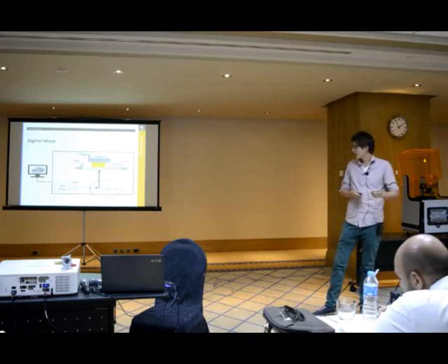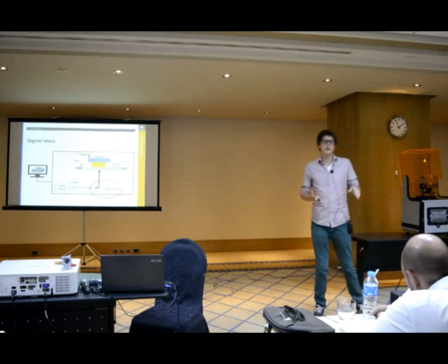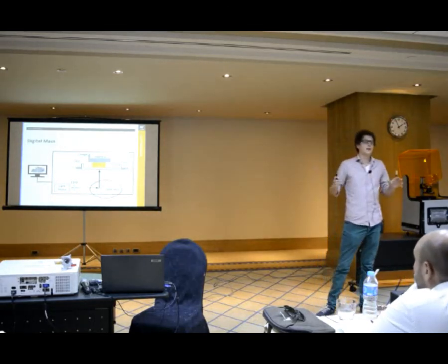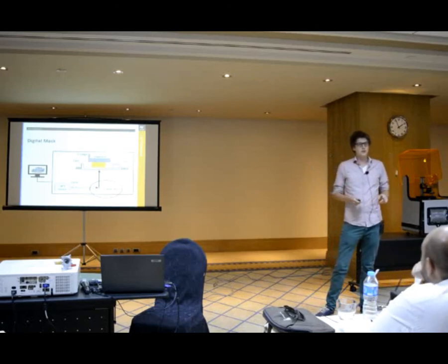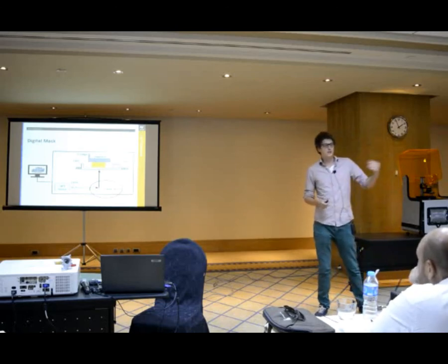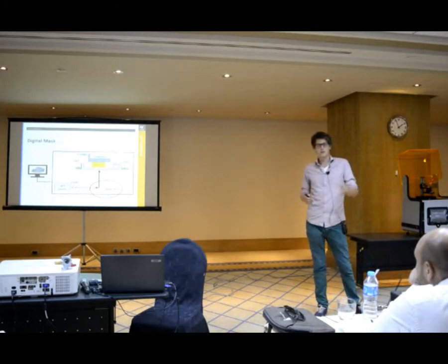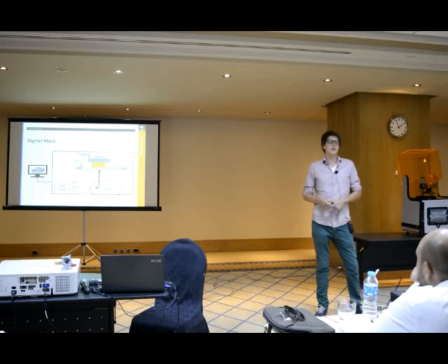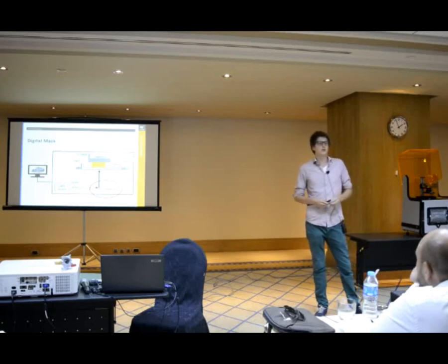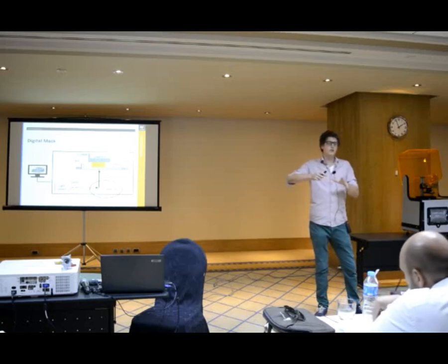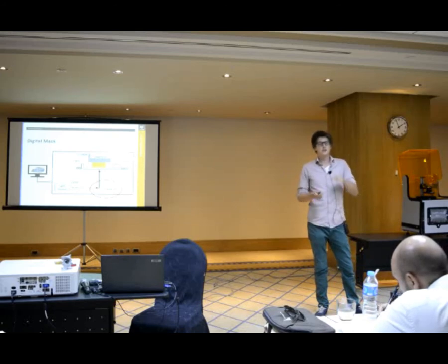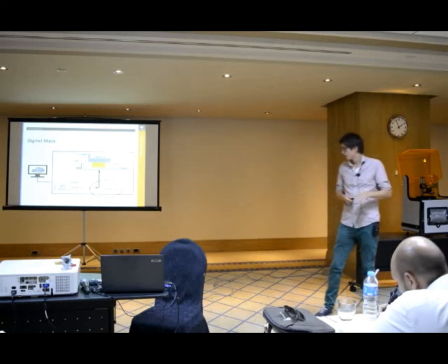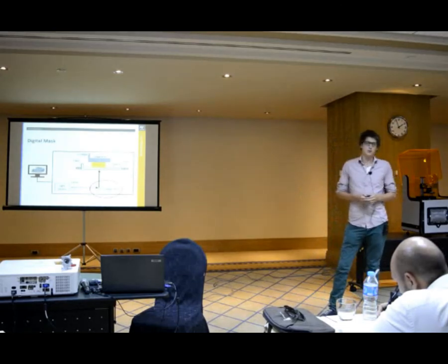Then we go to the digital mask. The digital mask makes your pattern, and you can envision it as an array of many tiny mirrors. These mirrors either reflect the light towards the resin, and the resin will be cured, or deflect light in another direction, and in those locations the resin will not cure. So these mirrors altogether will make the shape of this 2D slice, and make your resin cure at the right positions.